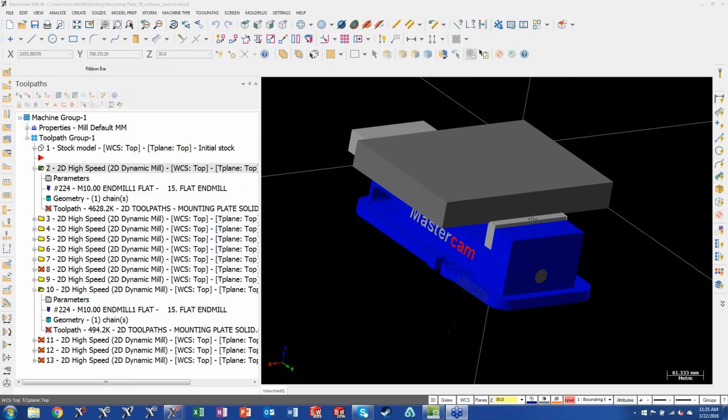Maybe a setting on your side, the diameter shouldn't change the feeds and speeds with it locked, but you may have some options that override it. Yeah, I just changed mine, and it'll change your surface feet per minute because the diameter changed, but it should not change your feeds and speeds if you have it locked on. But there are some other defaults that you can have on that will alter that. We just need to take a look at your computer and see what options you have on.